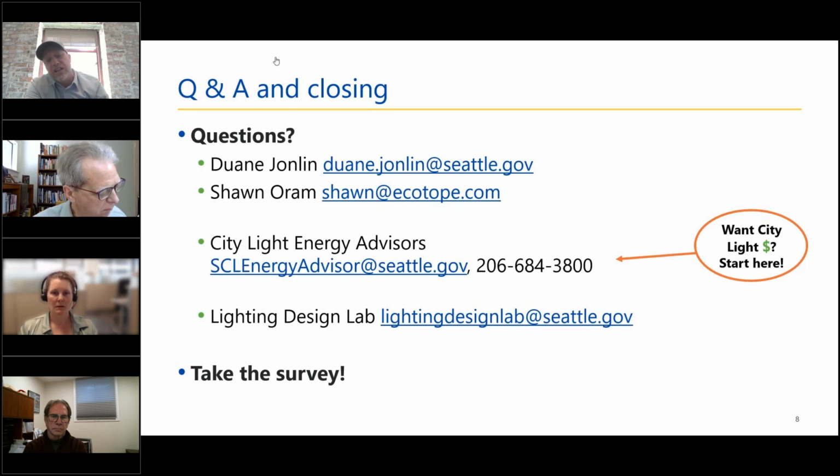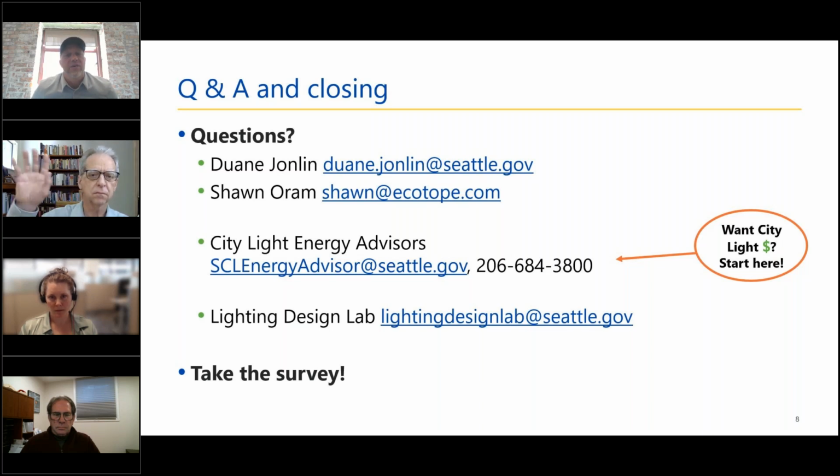What that leads to is variable supply temps. During big rushes you might be more in control, but when the system backs off, you're going to lose control. And control means trying to stick within 1 or 2 degrees of your supply output set point. You just want to make sure you don't dip too far. But a properly sized valve will be able to maintain control. Valve authority is the terminology.